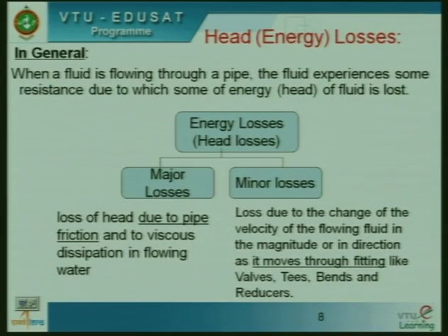The question is, sir, why do I need these losses? I will give a simple example. If you want to lift water from the sump to a 10-story building, suppose you use a cast iron pipe, and the capacity of the pump you are going to use is very small, can you expect delivery there at the top of the 10th floor? No chance. Why? In that case, your losses are more than the pressure developed inside the pump.